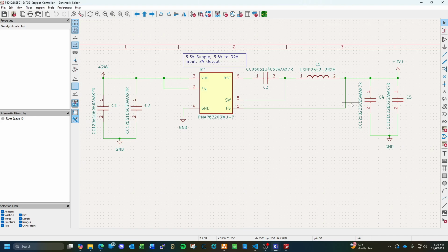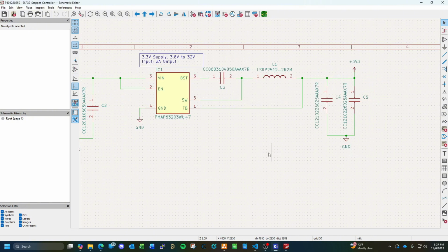This switching power supply design, I've used this in several other projects and I absolutely love it. I plan on throwing this exact same thing into other designs moving forward. A 2 amp 3.3 volt power supply is all you need, so we will be using this a lot. For me, being able to buy larger quantities of parts cheaper is a benefit.